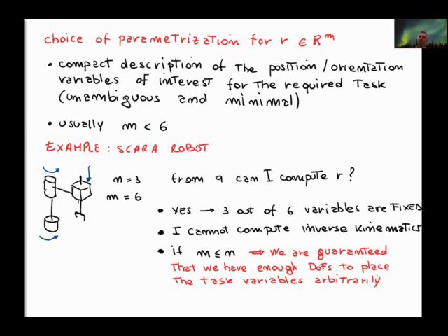So if you want to have a continuous trajectory for the orientation, and you have singularities in the representation that you choose, in your representation numbers you can get very big motions or jumps, or you can have multiple solutions. And this is, of course, a problem if you want to control the orientation through closing the loop on the representation that you choose.